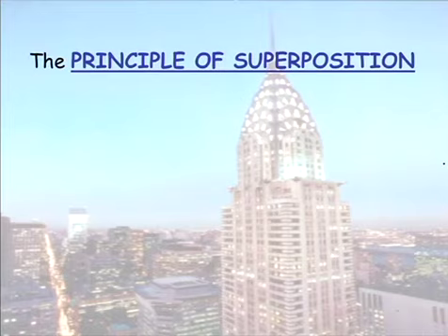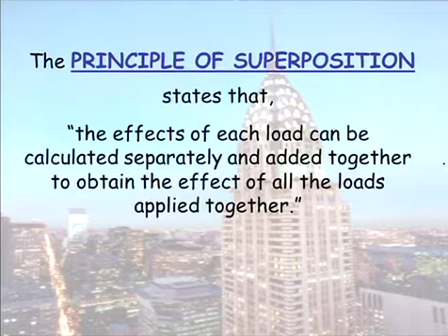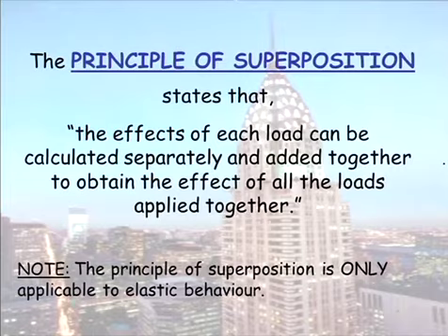But if I say I have my pen here because I forgot to bring my flexible ruler, and I push down with a kilo and it deflects down 1 mil, if I push down with 2 kilos, how much is it going to deflect down? 2 mil. Okay? That's using the principle of superposition. The effects of each load can be calculated separately and then added together to obtain the effect of all the loads applied together. So this principle is only applicable to elastic behaviour, linear elastic behaviour.